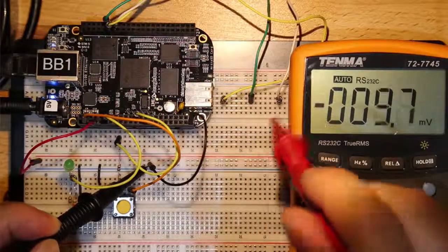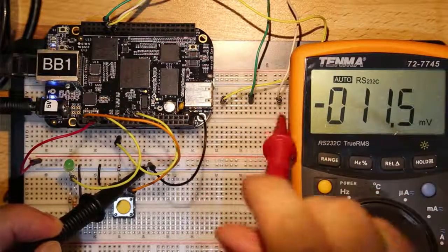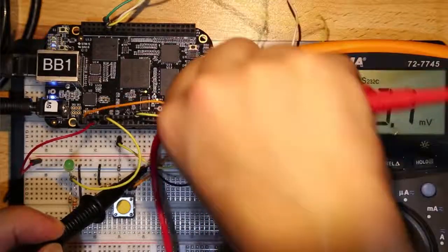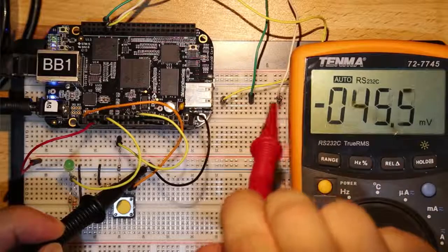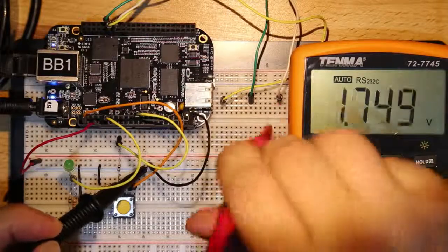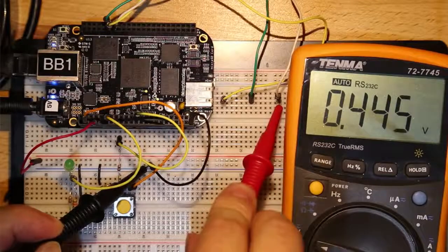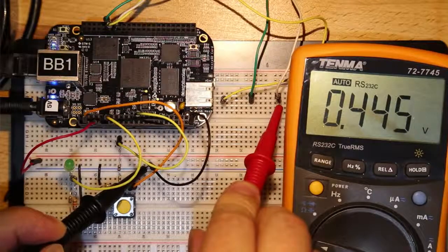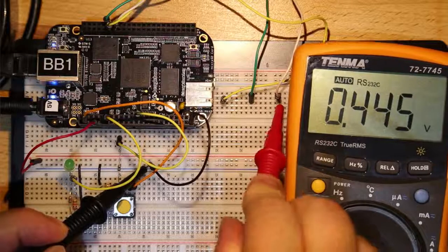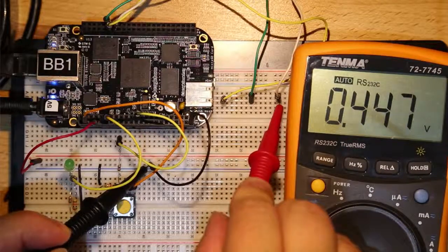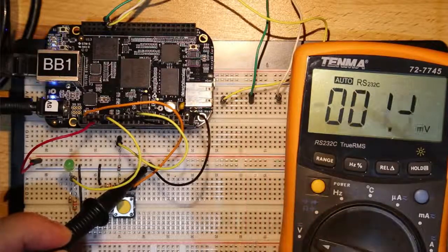And finally, the white wire has no internal connections, so no internal pull-up or pull-down connections. So if we measure the voltage on that, just get a bit of the metal visible. Just do this at a distance. You can see that at this we're getting 0.445 volts. So this is effectively floating as an input. So we would need external pull-up or pull-down resistors to drive correct voltage levels with this pin. So I'm going to concentrate on the first two first.